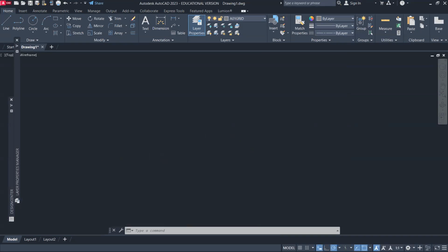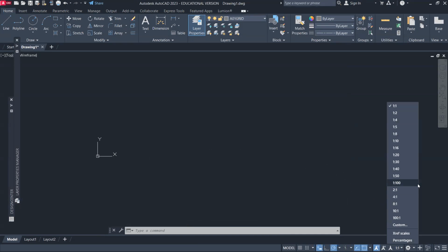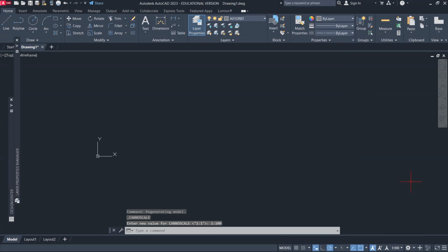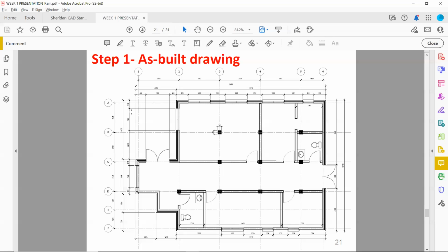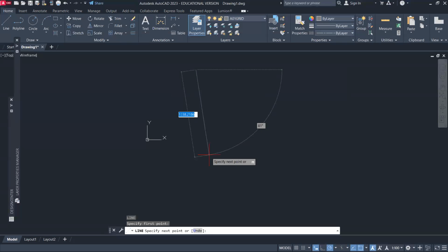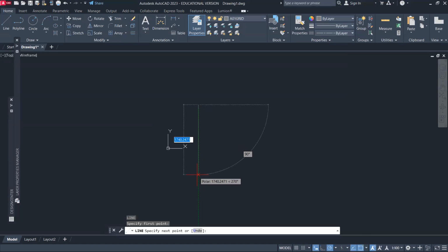Okay. Now from here, we can create our grid. Since we want this to maybe print at scale 1 to 100, we'll select that. And then we're going to create a line, the distance for which is about the length of the total. I might not know the total of that. That's okay. I'm just going to create a long line, let's say 20K, 21 to 3, which is about 20